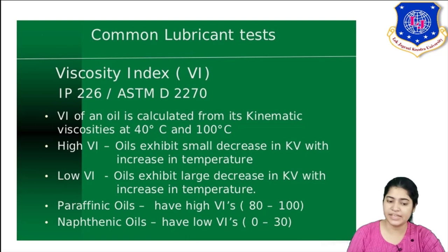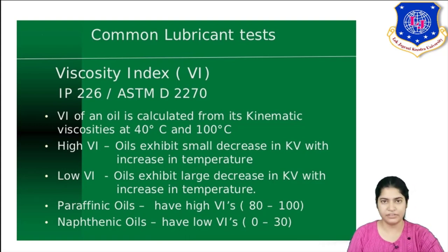Low viscosity index means your oil will exhibit a large decrease in kinematic viscosity with increase in temperature. So I can say high viscosity index means less temperature sensitive, low viscosity index means highly temperature sensitive. So paraffinic oils, the viscosity index range is 80 to 100.